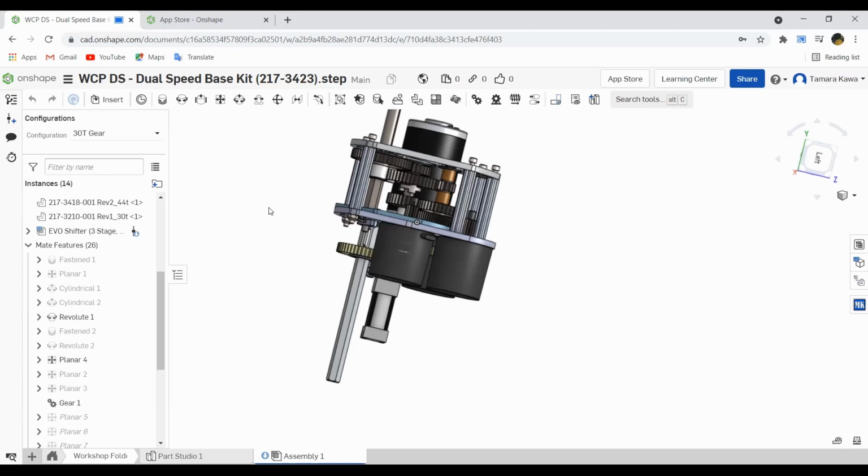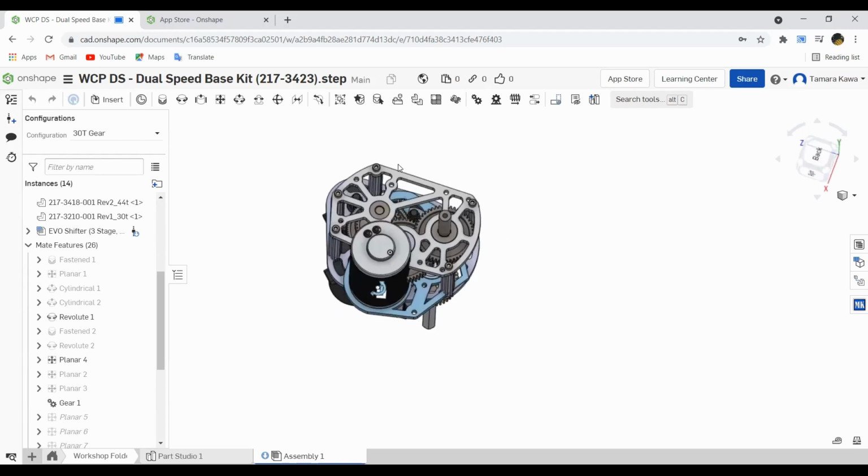It's kind of like, for certain parts, it is possible to just create a cross section and then revolve that versus creating an extrusion and cutting out all the little cuts you need to make. You could just do it that first way where you have this one cross section and that's it, but then that doesn't really tell you what order things need to go in. So part of it's an organizational thing. There are some cases where you might prefer to group things, and that's okay, but generally you want to work with mates.